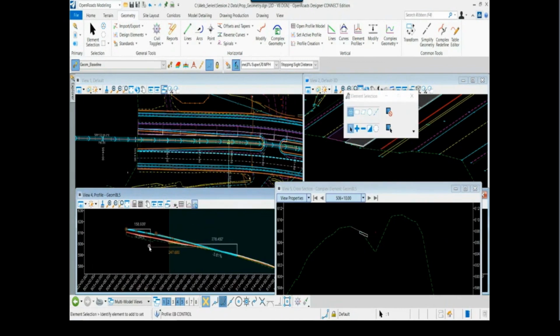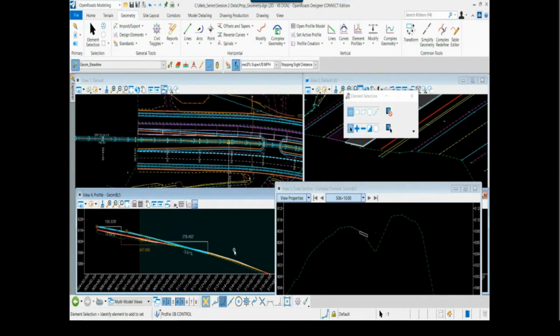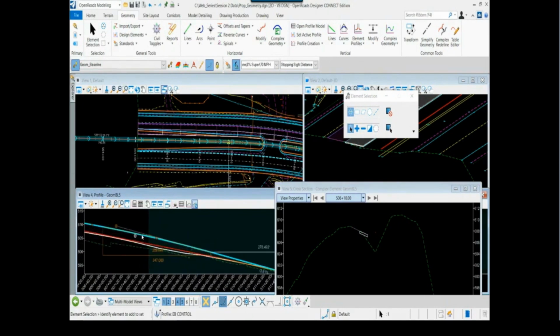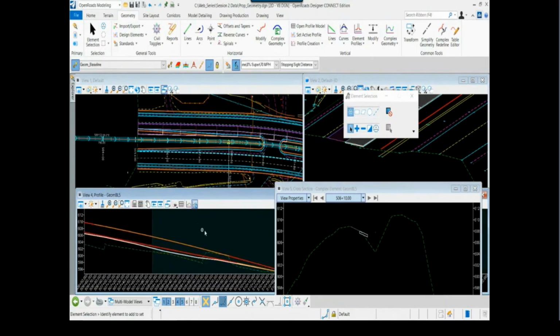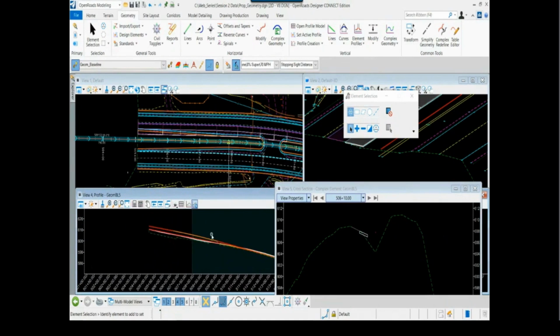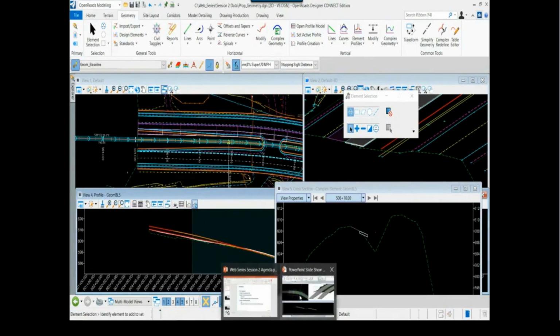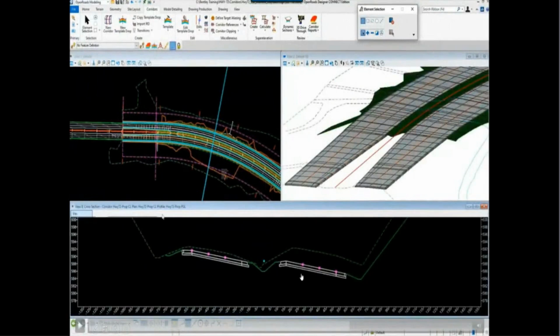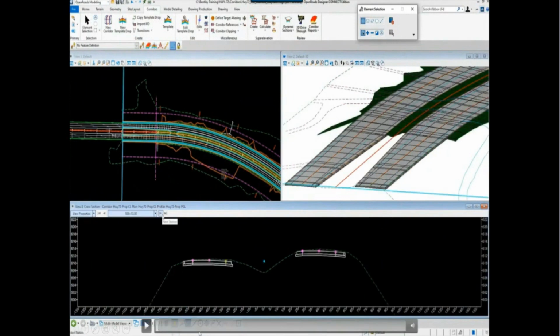Okay? So through this process, I know we're about 5 minutes over, but I wanted to make sure I get that control line in there and show you how I'm accomplishing that. Again, ultimately, the point here for all of this is to look at the objective of where we're going with the modeling next week. So in our session, we created the baseline, the horizontal alignment, and we created the PGL, of course, to control the overall roadway corridor that you see here.